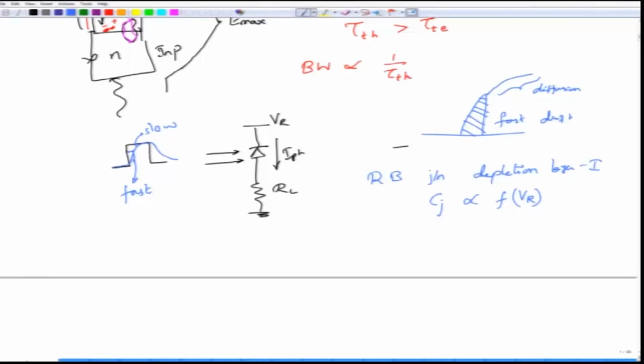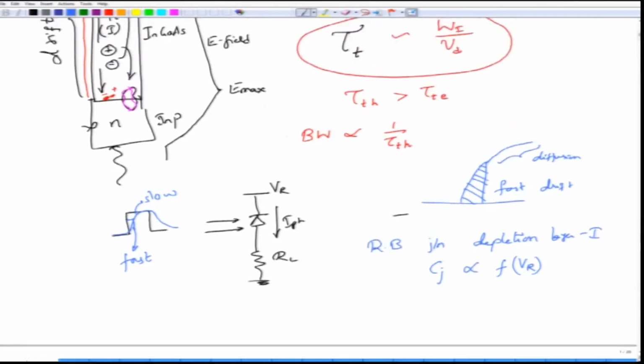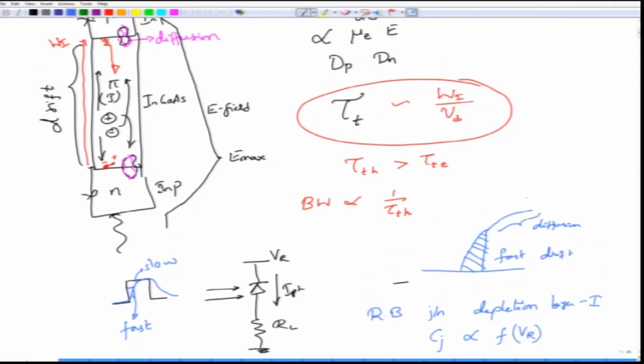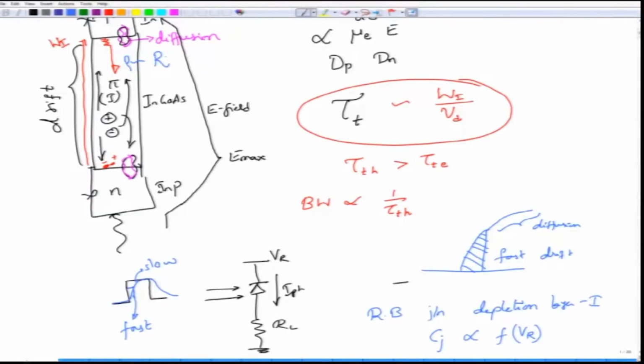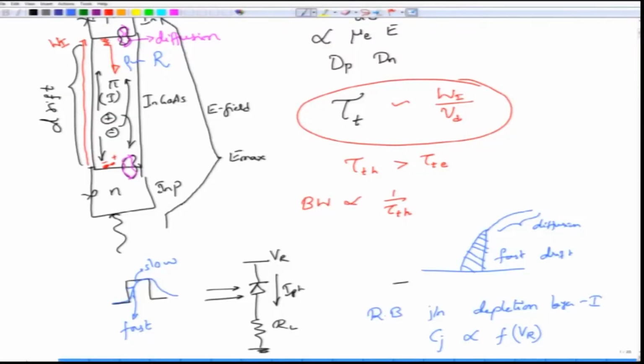There will also be some amount of conductivity of the material in the I region. I am talking only of the I region response here. So, there will be some conductivity or equivalently some resistivity rho. Resistivity rho, depending on the semiconductor bar, the width and the geometry of that, will give rise to some amount of resistance R. So, even if your external resistance RL were made infinite, so that it is not loading the photodetector, not exactly in this configuration, but in the op amp TIA configuration, which we will discuss later.